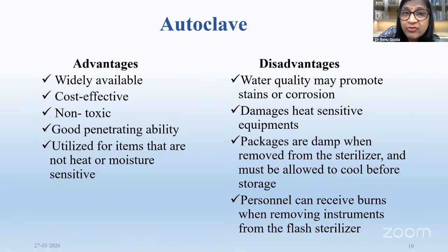And sometimes when you are removing the items from the autoclave, the packages can be damp. If the packages are just lightly wet, then it is okay. But if they are very damp, it means the steam is not dry. We need very, very dry steam. We do not need any air water mixture. The load which is coming out of the autoclave should never be wet. Light dampness is allowed, but it should not be wet. Otherwise, there is some problem with the autoclave functioning. And there is always a risk of burn if the entire pressure is not released before opening the autoclave.